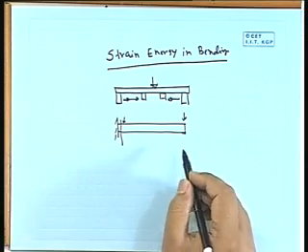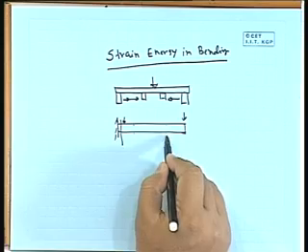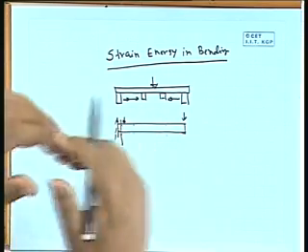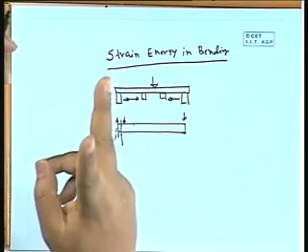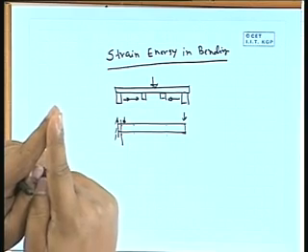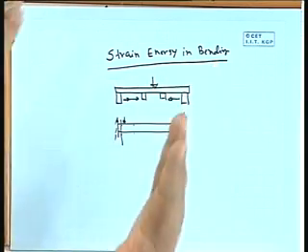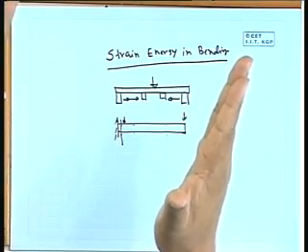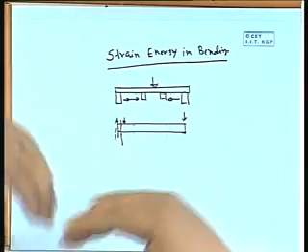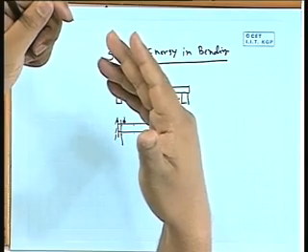So, it depends basically on the depth versus this length. Once this length is more compared to this, bending will be predominant. If this length is very small compared to this, it will be in shear mode. When we cut a piece of paper by scissors, two forces we are putting more or less on the same point with a slight shifting. If we put two blades, it will never cut, it will be under bending. So, when length is more, your bending aspect will be predominant. When length will be small, it will be in shear mode.